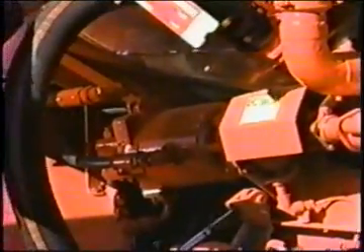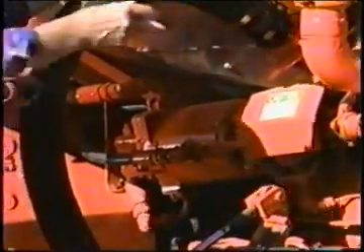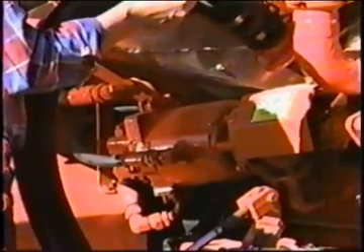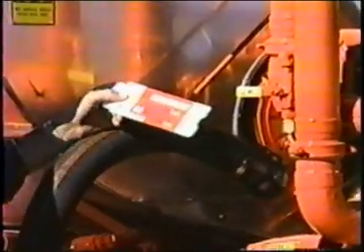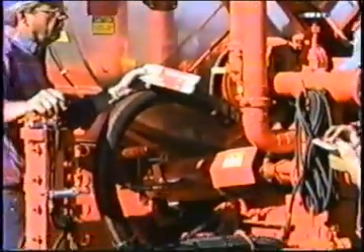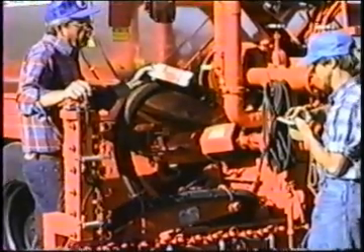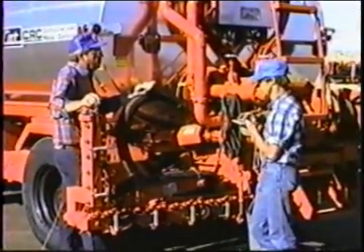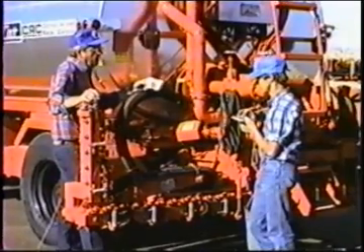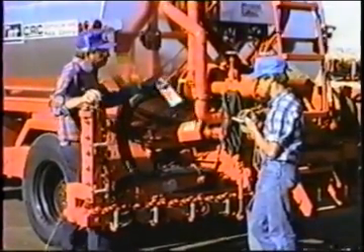We can drive the truck at our setup speed. Here we were setting up at 400 feet per minute. So if we drive the truck at 400 feet per minute, as we hold 400 feet per minute, regulate the pump to the 135 gallons per minute, and the setup is made.